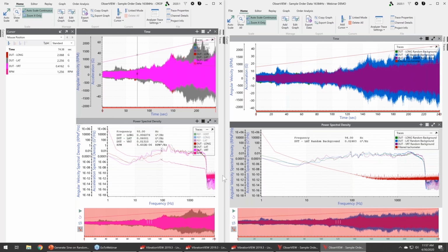What should be the exaggeration factor while creating an accelerated profile? Depends on the product. So there's ways to evaluate it, looking at the SRS of the long time history and making sure you don't exceed 10x of the SRS or 5x of the SRS.